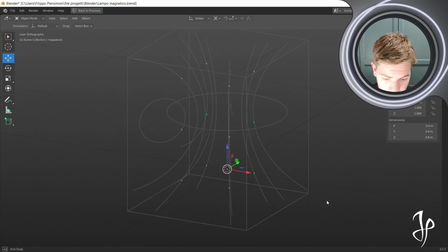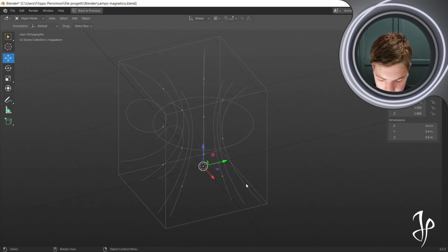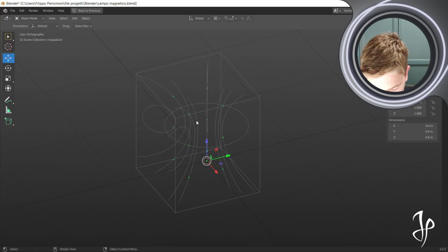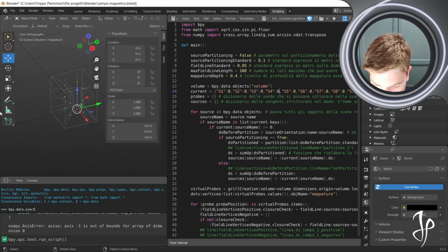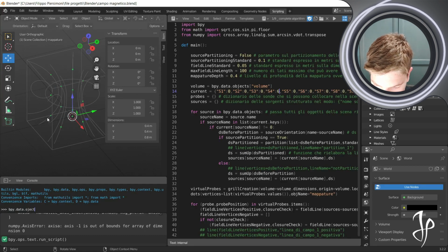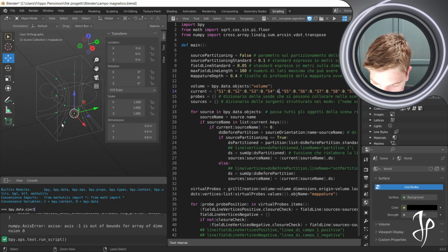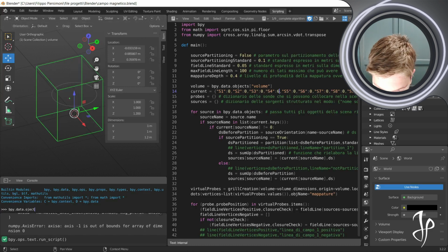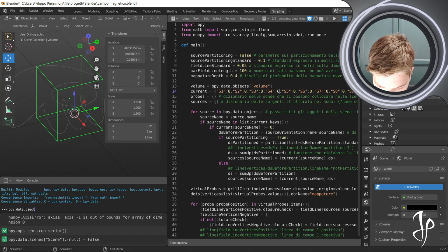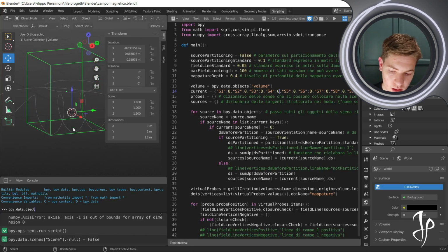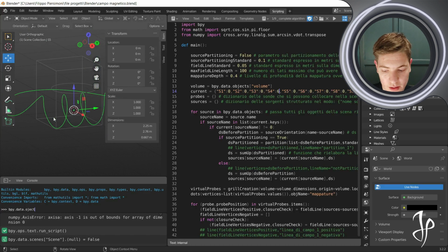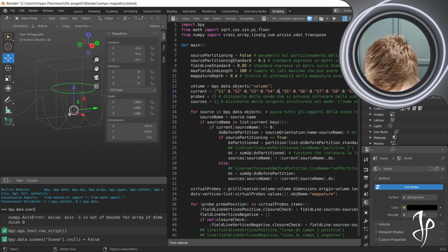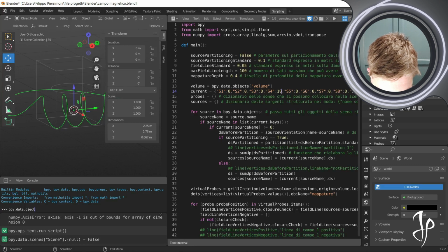And this is definitely useful to visualize all the magnetic field in the volume. Let me just do some more examples. Let's delete this. Let's see what happens if now we combine the two effects given by source number 4 and source number 5. Let's bring them both to 10 ampere. All right.